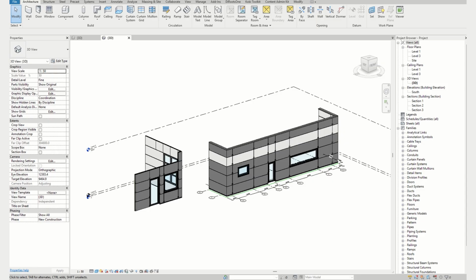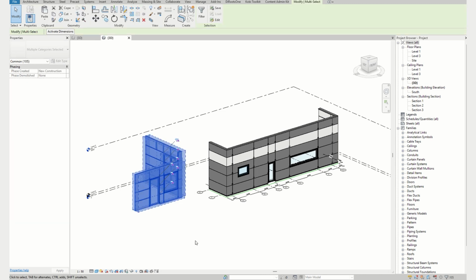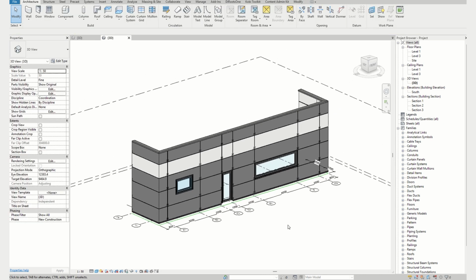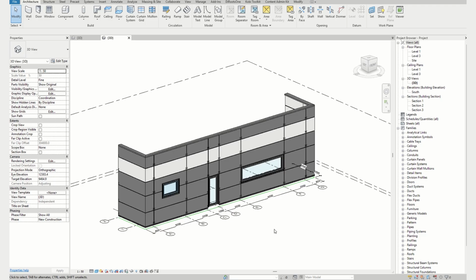Okay, so we're done with modeling and panel definitions. Now we would like to order all materials for our facade. Let's do that. We will do the schedules for all Qbiss elements in model. Let me just delete this copied part, which we don't need anymore. Now, let's check if all Qbiss elements are within limitation for production.